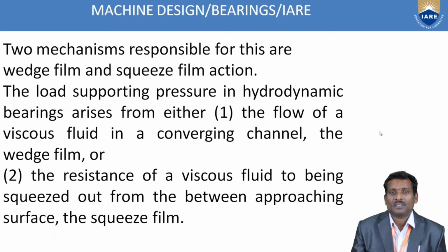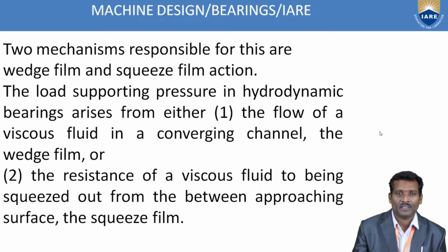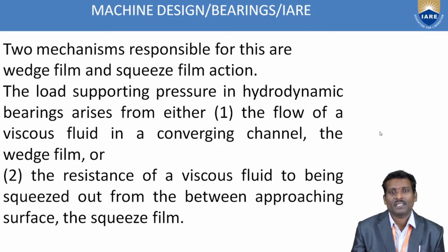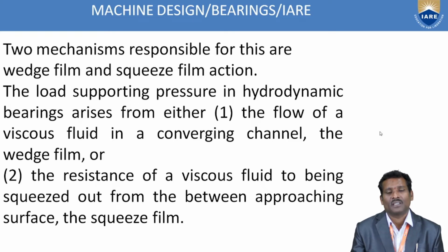The first mechanism is the flow of a viscous fluid in a converging channel. That is the wedge shape, as we discussed in the previous section in the hydrodynamic lubrication diagram, where the pressure distribution occupies the shape of a wedge. That is based on the flow of viscous fluid in a converging channel.